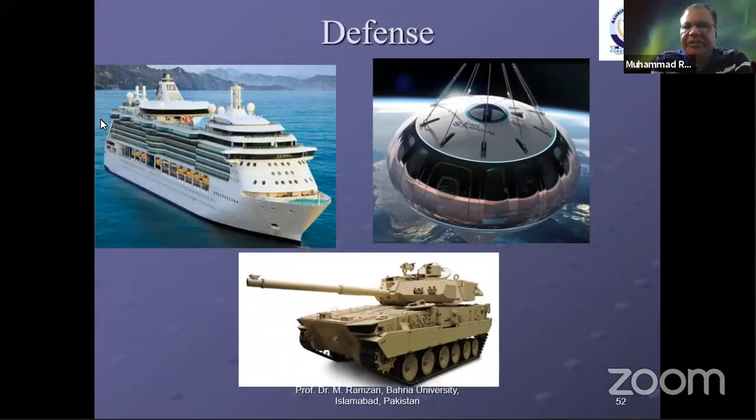Use of the nanofluids in the defense systems. A number of military devices and systems require high heat flux cooling levels of tens of megawatt per meter square. At this level, cooling with conventional fluids is challenging. Examples of military applications include the cooling of power electronics and directed energy weapons. Directed energy weapons involve high heat flux of more than 500 to 1000 watt per centimeter square, and providing adequate cooling of them and associated power electronics is a critical need.